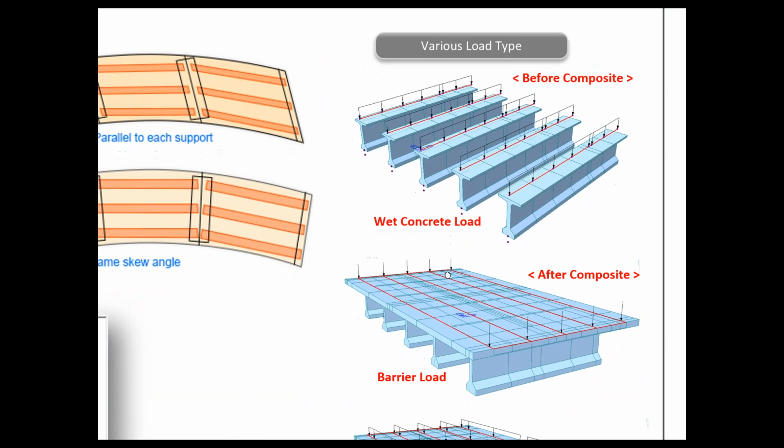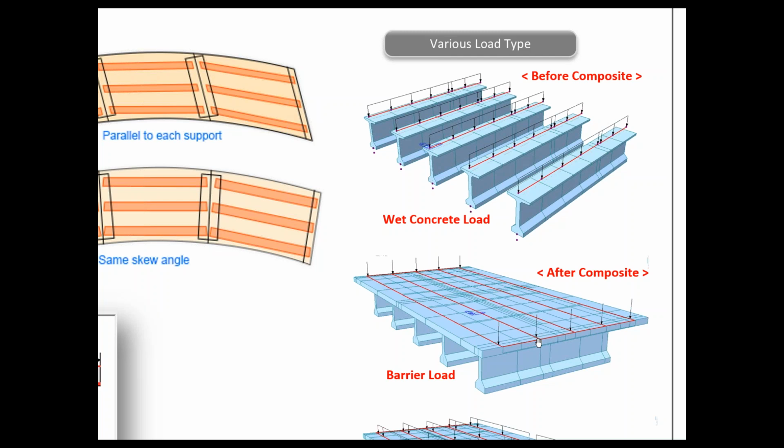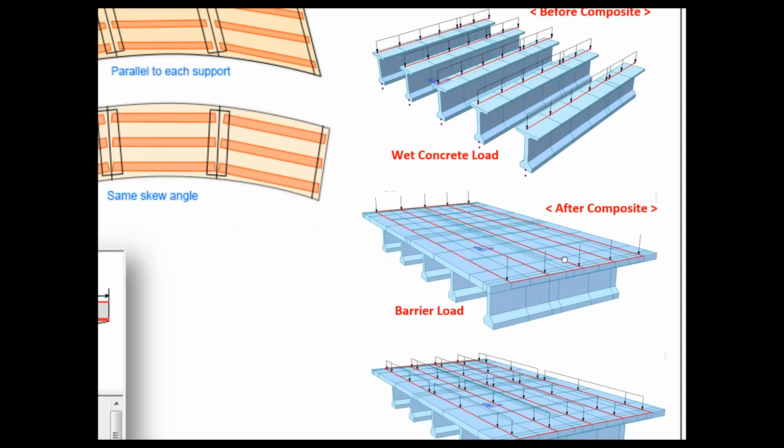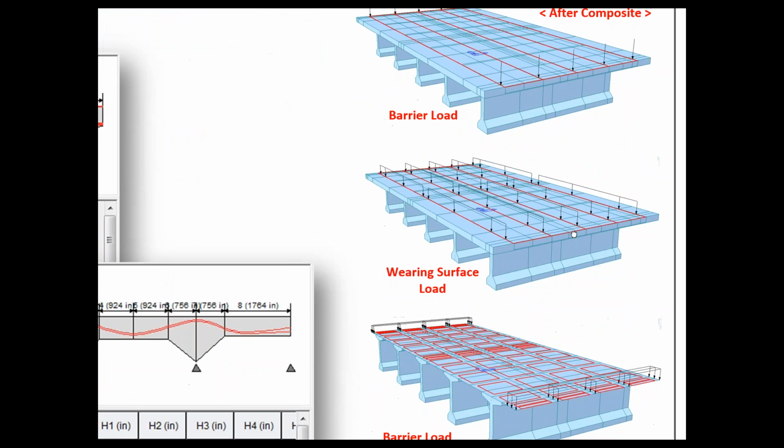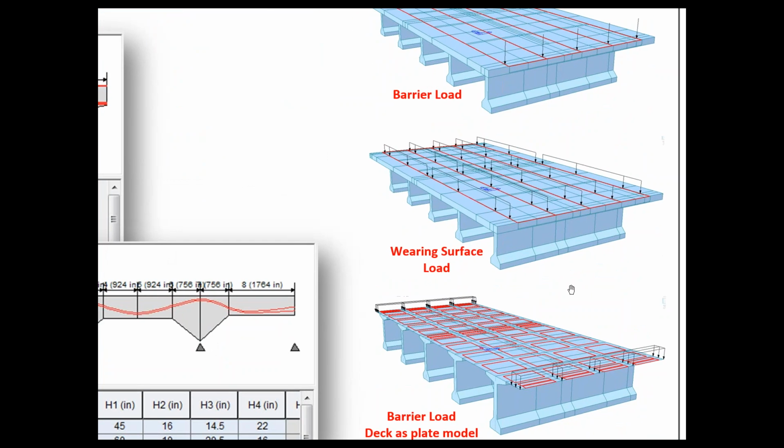And when you define your loadings, dead load, and various superimposed dead load, it's going to apply them in the most proper format, like this. So if you, within Civil or in any other program, were ever curious, like, oh, I punched in this loading, but how is it being applied? You can actually visualize it within your model of Midas Civil, just like this.